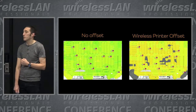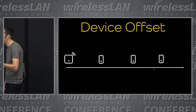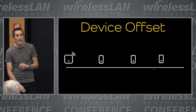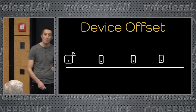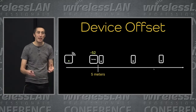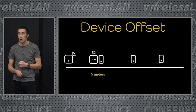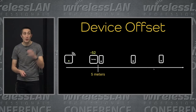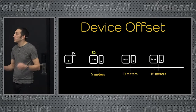So how do we go about measuring a device offset? Well, in one sense, it's quite similar to doing a design offset, except this time we're going to be comparing our survey device with a real device. And again, I would do it at multiple places. Now, where would I do it?